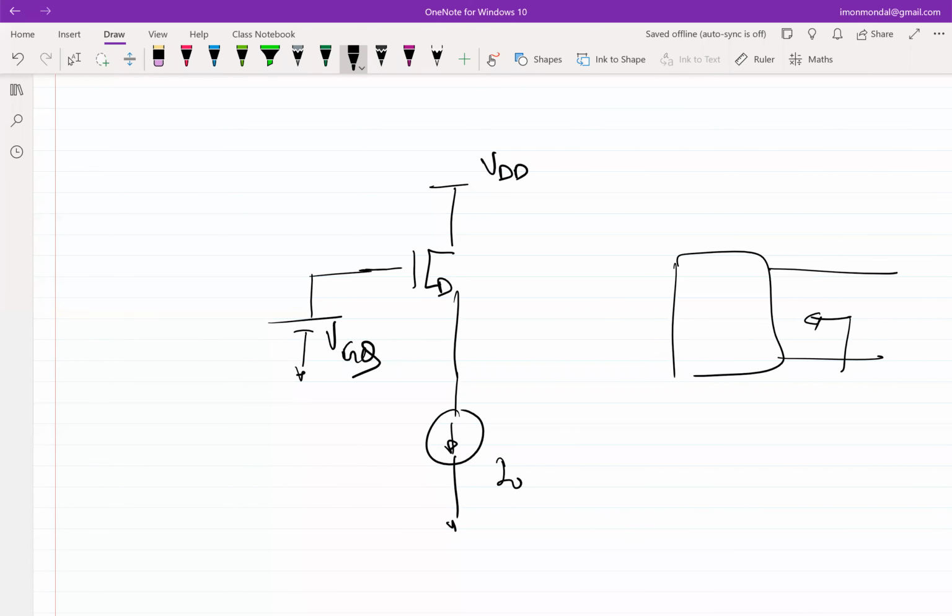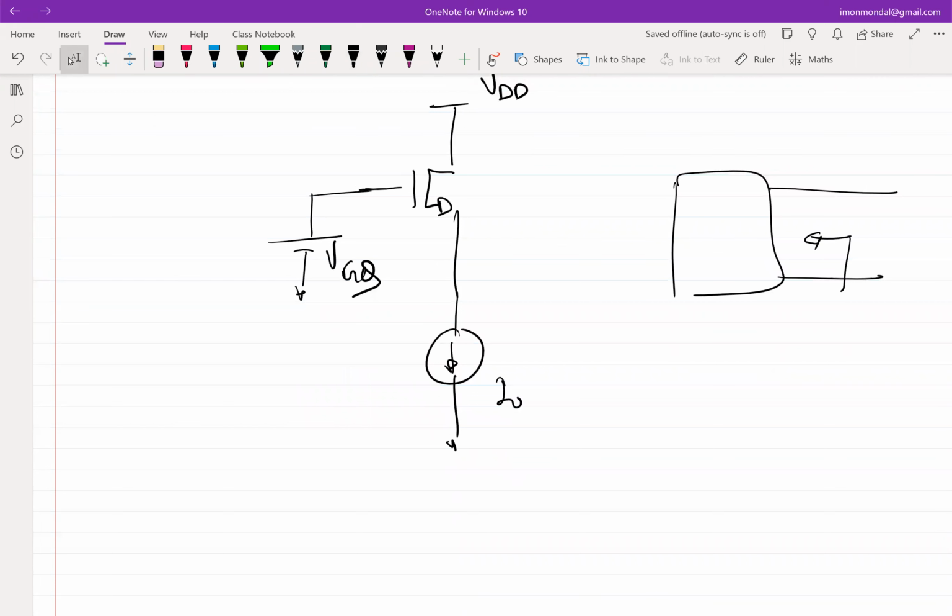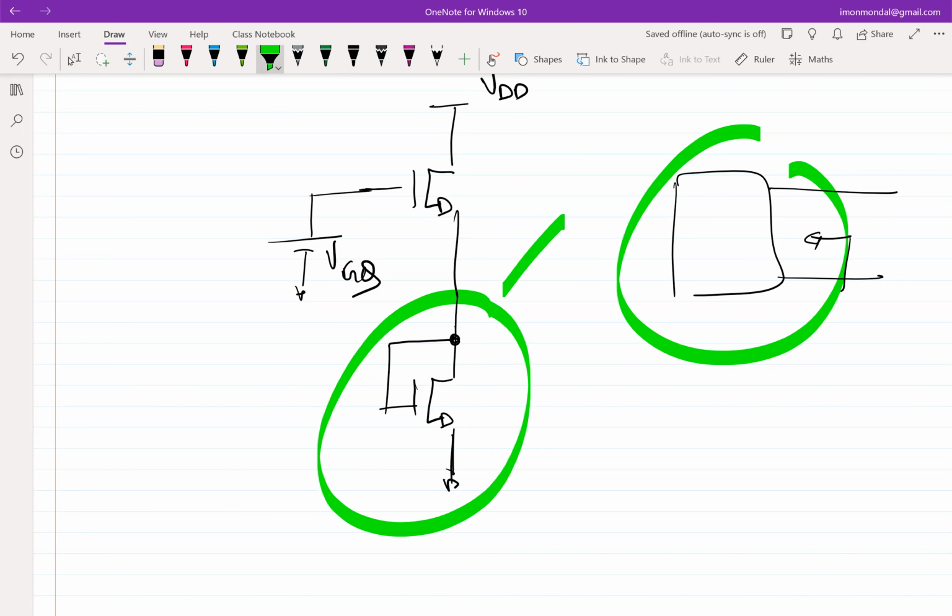Not really. Okay, so let's do the diode connection. So he's saying that if I put a diode connection here, this is what you're saying, correct? Okay, so let's try to figure out the impedance of this diode connected stuff. Now this stuff inside the box I'm looking in is essentially looking here. I'm trying to figure out what is the impedance looking down. So what do you think is the impedance looking down of a diode connected device? I think this was again a part of one of the tutorial questions, not in this sense, but in some other sense.